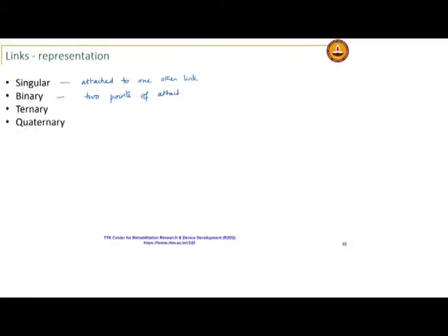In real life links may have complex shapes, but as far as the kinematics are concerned, we are only concerned with how they are attached to other links. A binary link connected to 2 other links by revolute joints would typically be represented like this. It has 2 nodes. A ternary link similarly has 3 nodes, a quaternary link 4 nodes, and so on.